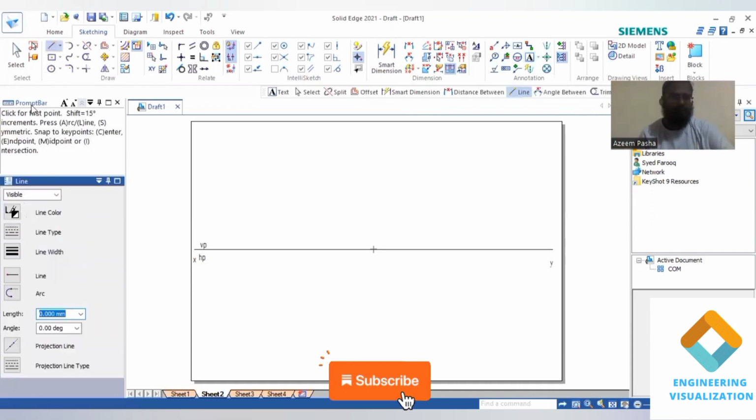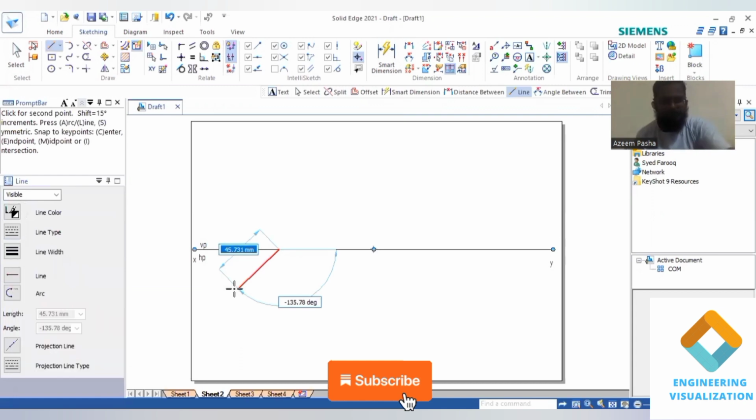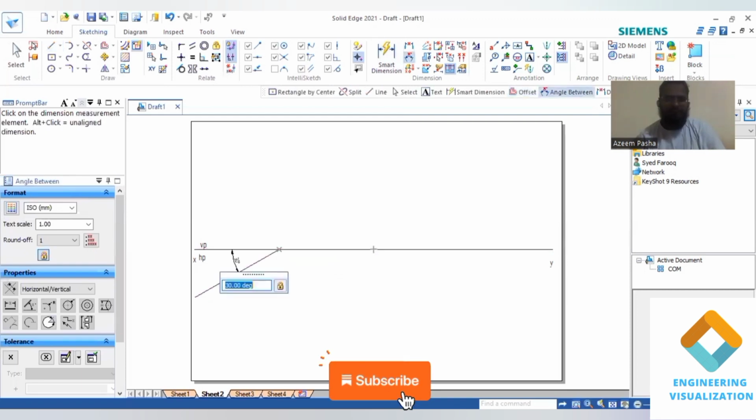Now you draw an angle line. Here you should draw an angle line for 30 degrees. So 30 degrees means below the XY line you should give an angle of minus 150. If you give 150 as the angle, you get 30 degrees here. You can measure the angle by using the angle between command, so you will get the angle 30 degrees.